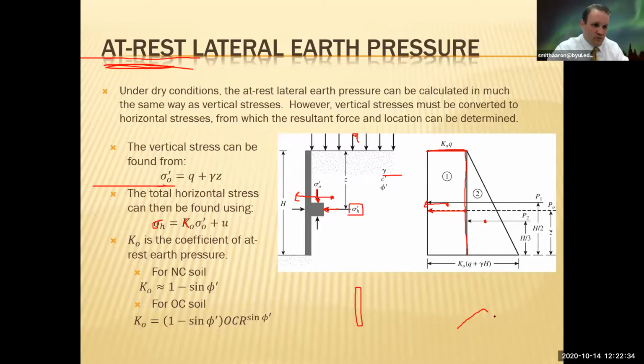So this is what a stockpile would look like with the sand with a 30-degree friction angle. But this is what the stockpile would look like if the sand had a 45-degree friction angle. If you put a wall on this, it's holding up a lot more than if you put up a wall on that one. The triangles don't look proportional, but the sand with a higher friction angle can hold more of its own weight, so there's less acting in the horizontal direction, if that makes sense. Any questions about that?